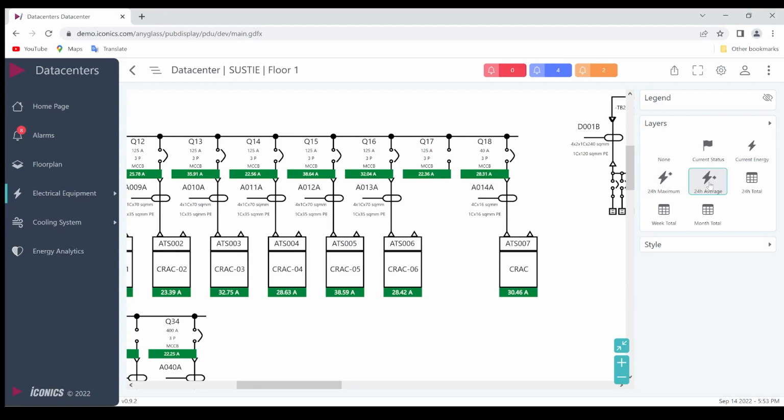Look at, what's my average. Quite often people will set a parameter to look at, what was my peak current in a circuit over the last month. Always looking to see if we're approaching any possible trip based on our current workloads.